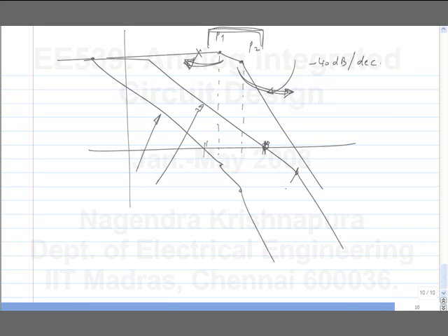What's that? Yeah. So one is, of course, the very small conductance means very high resistance. We may not be able to implement it. What else? The area increases. What happens to noise? So if you increase the impedance level, the noise can increase also. Or you have to increase the capacitance, and then you have the same problem. If you try to implement a very large capacitor, you will end up wasting area, which may not be possible.